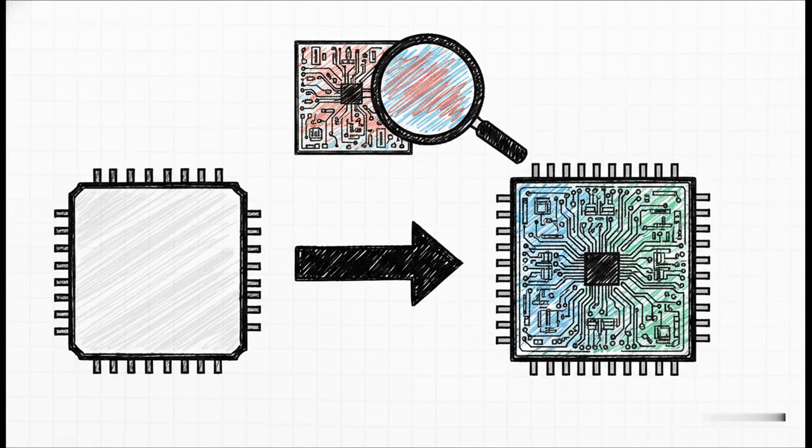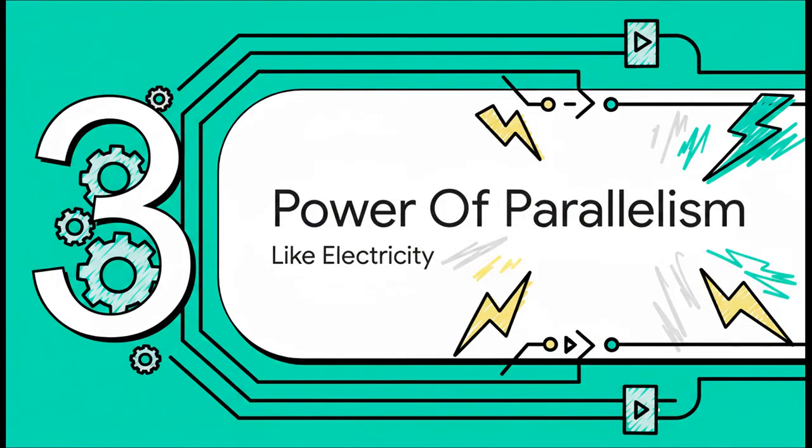Because of that, this code doesn't just run like a regular software program. Instead, it's used to design complex digital circuits, things like adders, counters, or entirely new CPUs. Engineers use it to model hardware before physically building it, and, crucially, to test that circuit's behavior using simulation. They also use it to program reconfigurable devices called FPGAs, field programmable gate arrays. These are basically blank slate chips you can mold into whatever hardware configuration you want just by uploading your Verilog code.